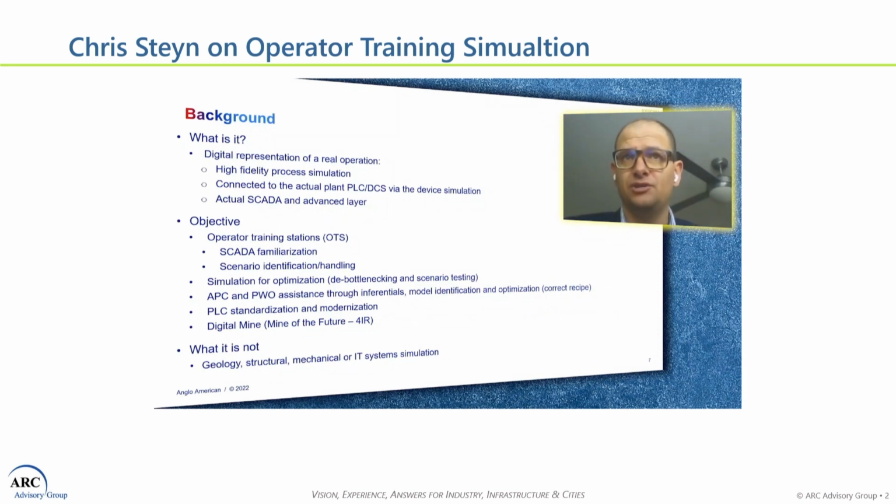It is a digital representation of the real operation, as we've said, but it entails a high fidelity process simulation, which is connected to the PLCs and the DCS via that device simulation. And then you can put an operator in front of an actual SCADA that is connected to the actual advanced layer on site. And you can immediately see the benefit that alone will have on any simulation.